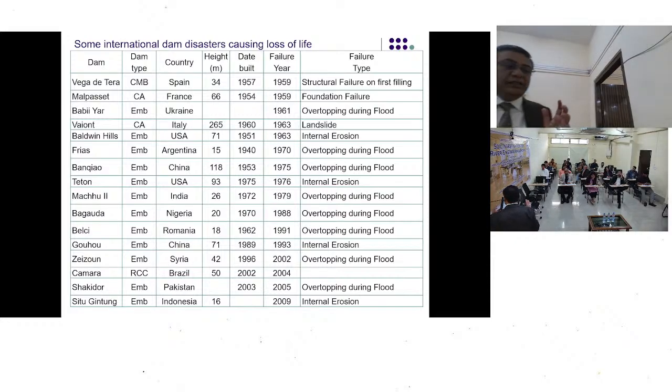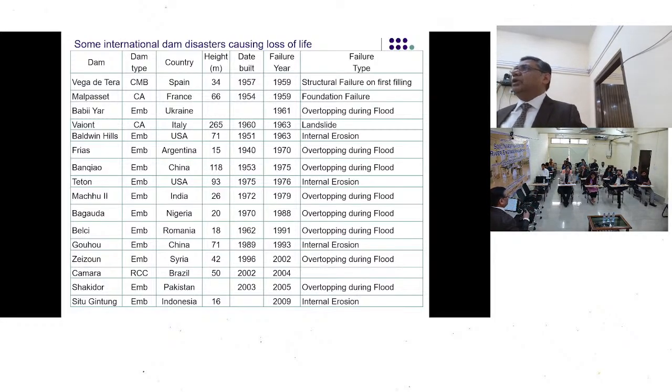So the engineers there reduced the reservoir level, and thereby the movement of the mountain came down to around maybe 0.5 centimeter per day. Again, they filled up the reservoir a little bit more, and they found that with every consecutive reservoir filling and lowering, the movement was reducing. So they became more and more confident that the geology had come to a certain equilibrium, and that they could operate the structure the way they wanted.